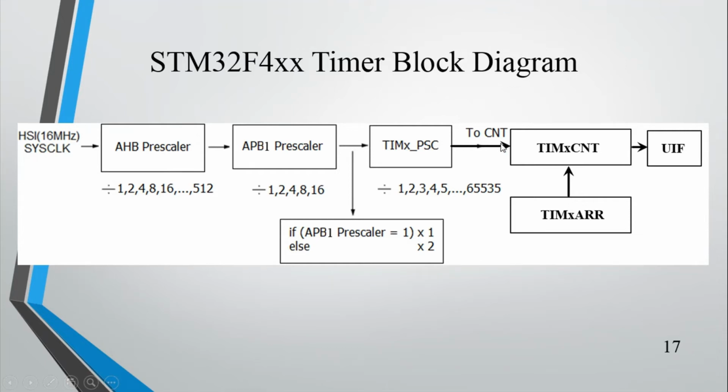Right. So maximum, if it is a 32-bit counter, you can count only from 32 zeros to 2 raised to 32, that is 32 ones. 32 zeros to 32 ones. Only that much counting is possible. But if you configure any of the prescalers with another value, if you configure this by 2, what will happen? When you get 2 clock pulses here, then only you will get 1 clock pulse here. So what does it mean? The total time delay is multiplied by 2.